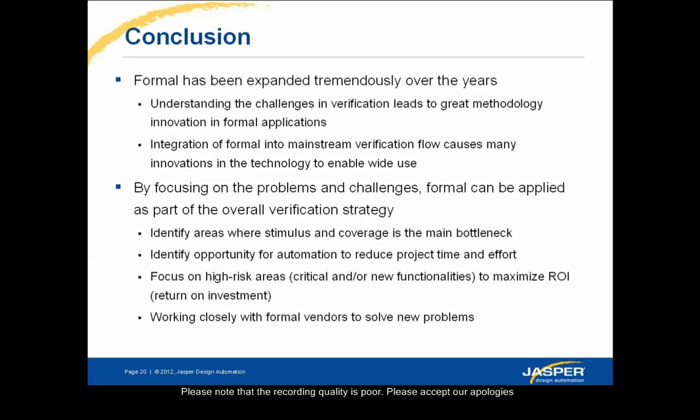Okay, so the question about coverage and formal is a very good one. It's actually the first question that I think Jeff Barrett asked me after I started back in February. Yes, we are looking at coverage. There is a coverage feature as part of JasperGold, which will be on mainstream release in the early part of next year. We were one of the companies that demonstrated, along with Mentor at DAC, integration with the UCDB UCIS database, which allows the cycling of coverage points between simulation and formal.